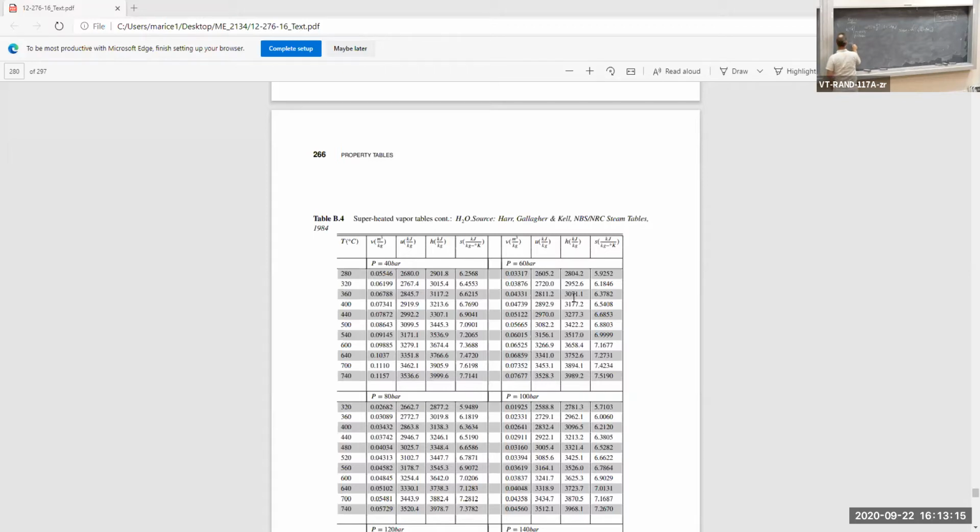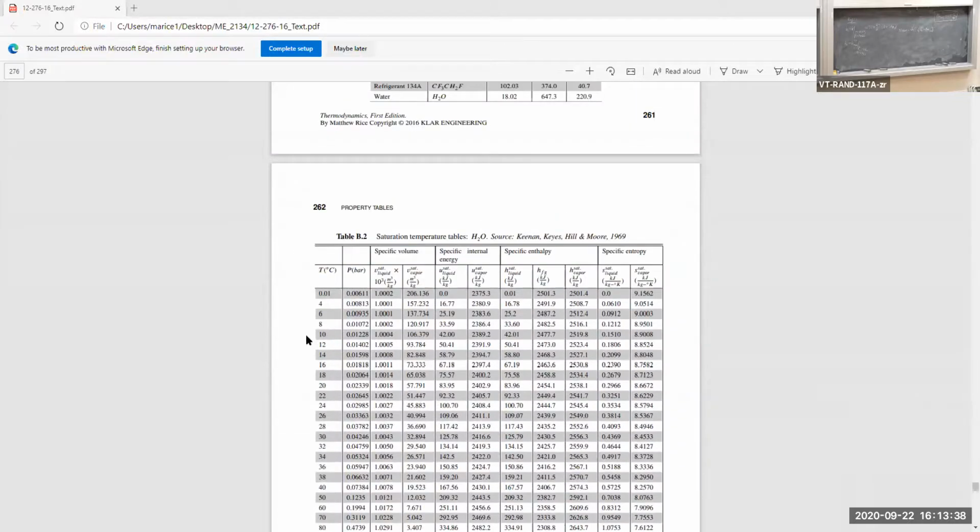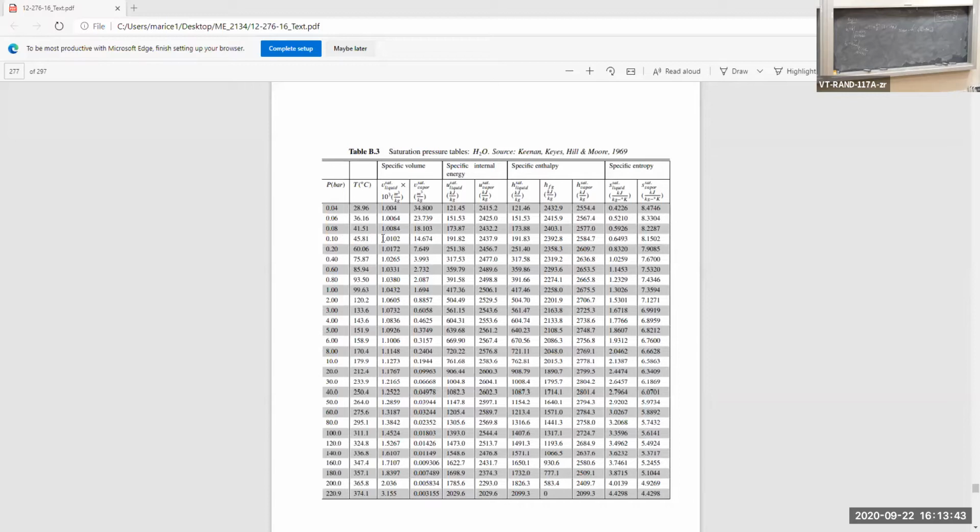What about H2? H2 is a saturated mixture. I have a pressure P2 equal to 0.1 bar, and a quality X2 of 92%. So we'll have to go to the saturation tables. Saturation pressure table, 0.1 bar. Here is H for the saturated liquid. Here's HFG, which is the enthalpy change between the vapor and the liquid. Use the quality, you can quite easily calculate H2. I won't bore you with the calculation here, I'm just going to put the value down. H2 is 2393 kilojoules per kilogram.